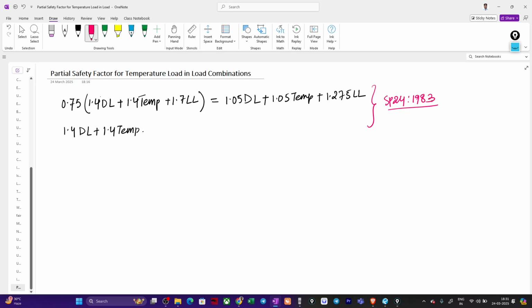What about the other loads? If you see IS 875 part 5 also, it gives combinations with no safety factor, that means considering 1 as the safety factor. For the ultimate design, it says that you have to consider the design combinations, I mean partial safety factors, according to our design codes and according to your engineering judgment. So it is also not clear.